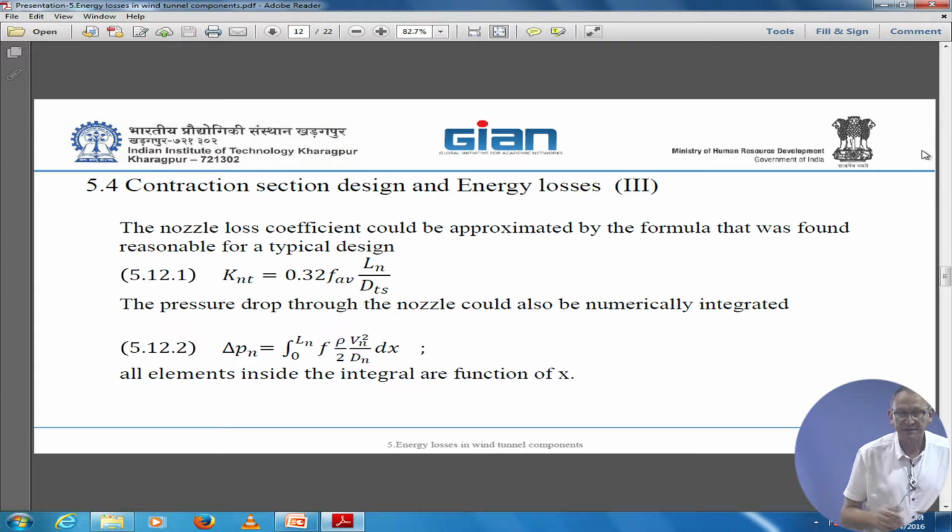We had all of this. So by mistake, they were running without the honeycomb, and even in a simple manometer, an inclined U tube at 30 degrees, they saw how the water fluctuated when the honeycomb was not there on the sensor that was next to the wall. Once they put the honeycomb, it's straight. So it straightened the flow.